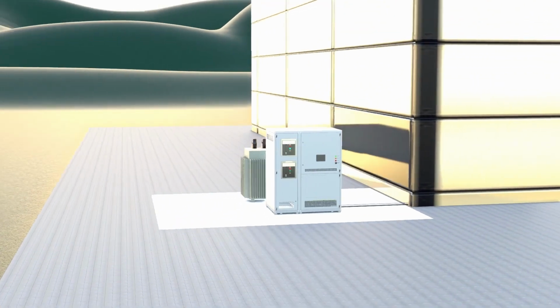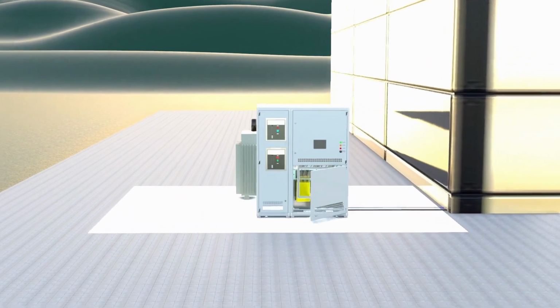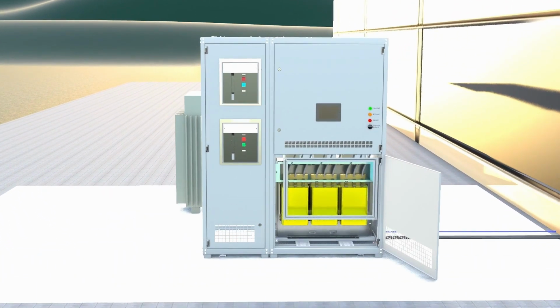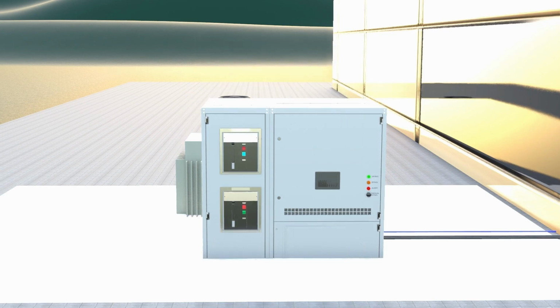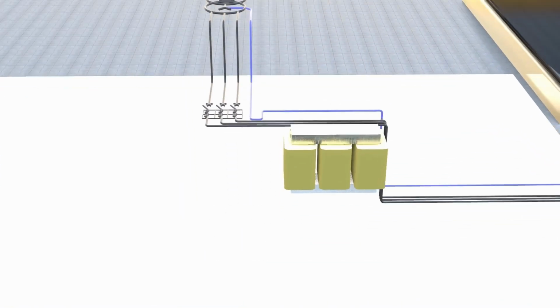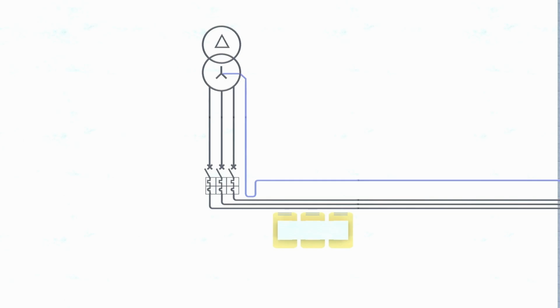From there, the transformed energy goes into the low voltage main distribution. Right after the medium voltage transformer, the efficiency filter is installed. The main component of the efficiency filter is a specially designed three-phase transformer. First, let's begin with the present state and initially disregard the efficiency filter.